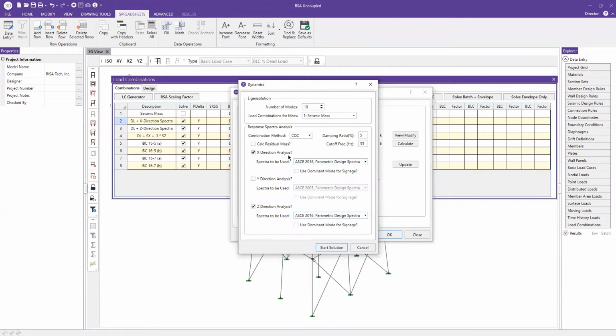So when using a combination of different modes, as I mentioned in my slides, if you have a square root of the sum of the squares inside your equation, then when doing the square root and squares, you lose your sign, your signage for all the forces, like your joint reactions or your displacement. So at the very end, you might end up with some very weird reactions at the node or some weird deflection shape. That's because when doing the combination, you lost all the signage.